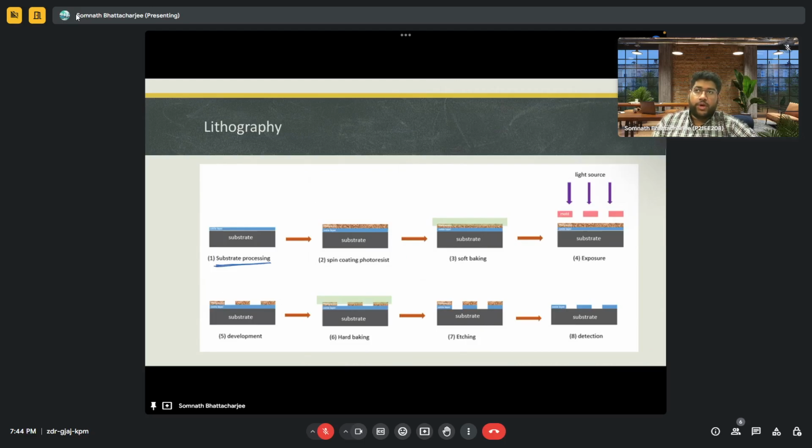Let's say, a coating of an adhesive material, which will just enhance the next process step, that is the PR coating or the photoresist spin coating technique. So there, on top of silicon wafers, there's a coating technique that is called the OTS coating. We generally coat OTS to increase the adhesiveness of the PR on top of this kind of substrates that can be silicon or those kind of things. In the silicon industry, the OTS is the most used liquid.